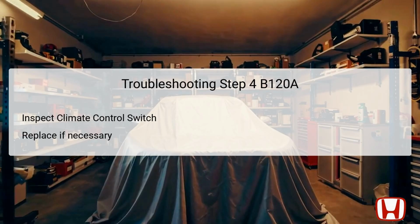Due to the absence of a direct testing method for this specific switch, it is recommended to use a known good component for substitution. By installing a known good climate control switch, a technician can observe if the initial symptoms are replicated again. If the problem persists with the new switch, it is likely that the issue lies elsewhere within the climate control system. However, if the symptoms vanish, the climate control switch itself is deemed faulty and requires replacement.